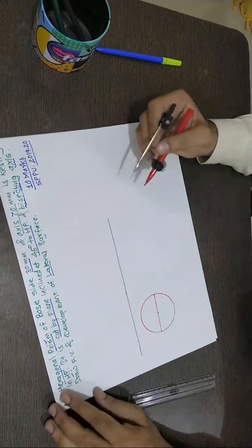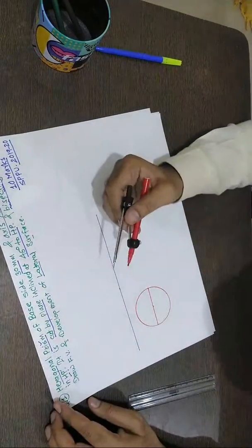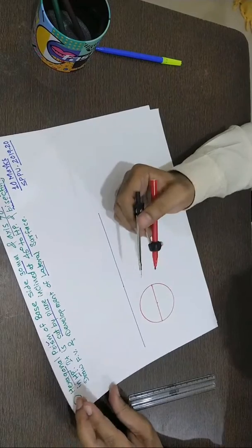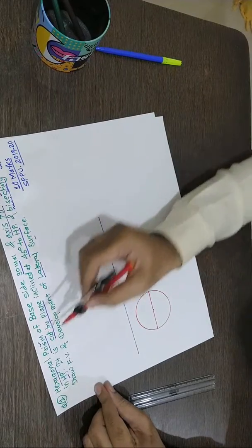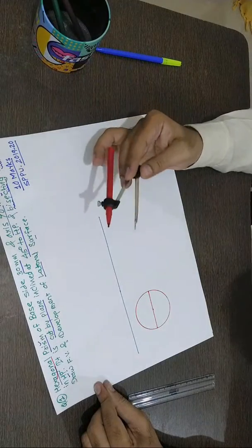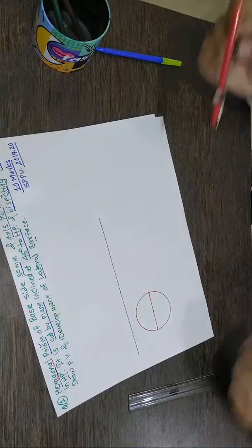First you draw one reference horizontal diameter. When you are drawing with a pencil, all this should be very faint, not too dark. We are interested in drawing a hexagonal shape, not a circle, but with this method you can draw a hexagon in the least possible time.